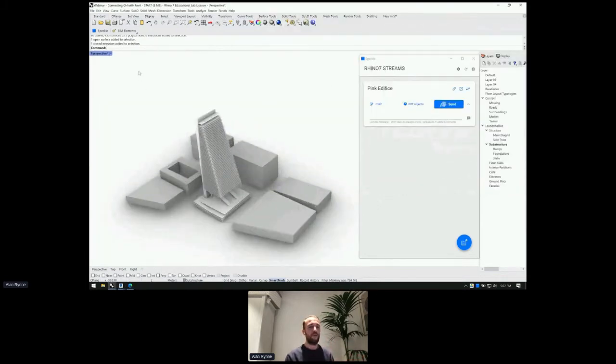So the first thing you will note is that we have this beam elements drop down in Rhino, and if you expand it, you will see the most basic types of Revit elements available to select: a wall, a floor, a column, a beam, a face wall, which is to create walls from NURBS surfaces, so you have a curvy wall instead of just a straight wall with a line. Then you have the option of specifying a direct shape, or the automatic option, which is the one that we're going to see first. And lastly, we have the remove Speckle beam from all selected objects, which would basically undo what we're about to do. So let's go ahead and select a couple of objects.